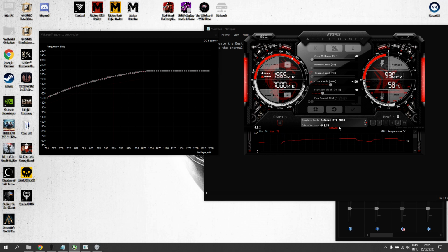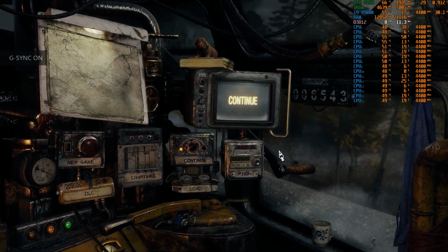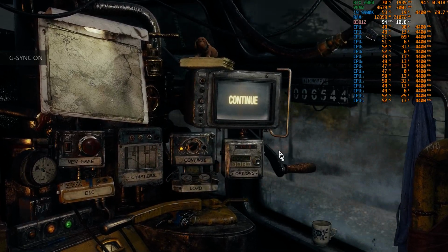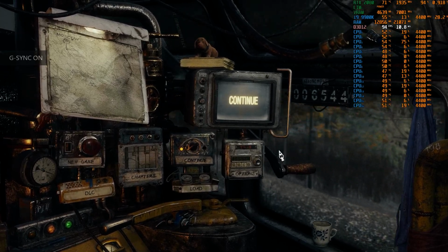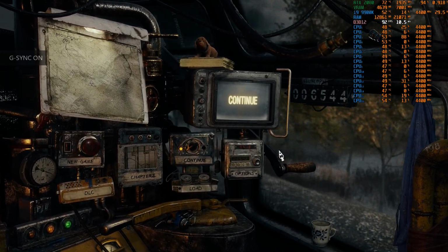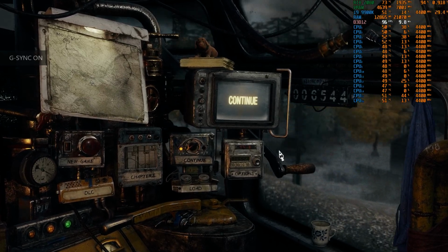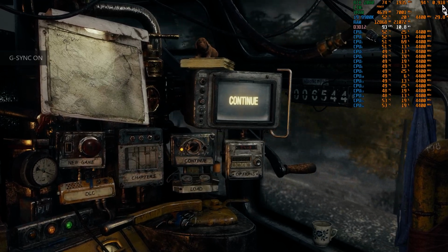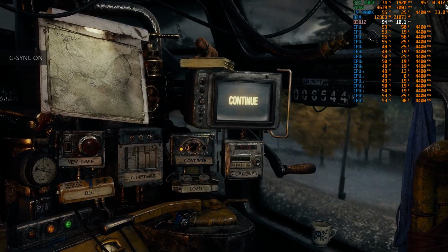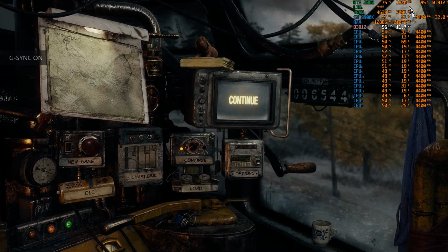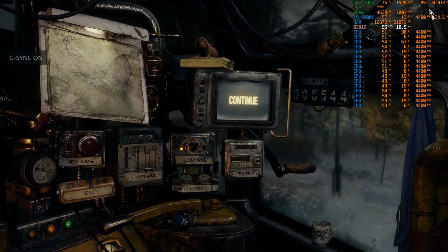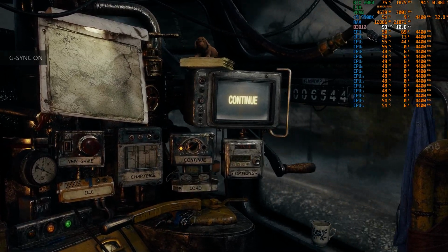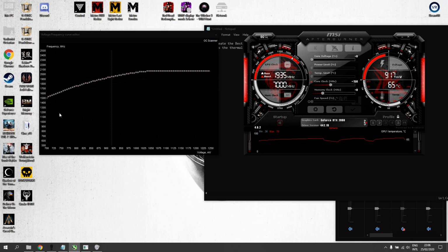L to lock, apply. What about now? Are you drawing too much? No, now you're not drawing too much. So I don't see the thermal limit. The power limit, I'm still seeing the power limit. So yeah, more than 0.912 as you saw is too much. So yeah, 0.912, as you can see, it's trying to power limit. So definitely once you hit the power limit, the temperature, that's fine, and now it's going down. So we are trying to draw too much.